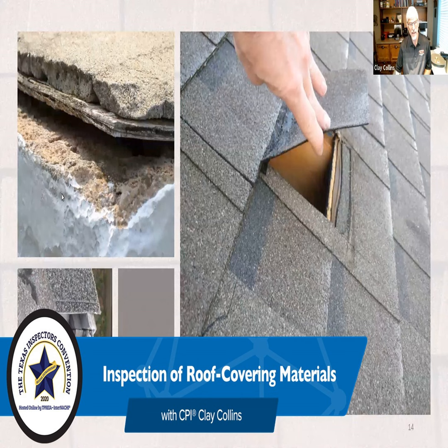Now, you should have a starter course, and the manufacturer allows you to take a shingle and cut it and turn it over and use it as a starter course. And then that adhesive strip is what catches the overlying shingle cover. But the biggest problem I see is that the fasteners for that are so far from the edge of the shingle at the eave that there's nothing holding it up.